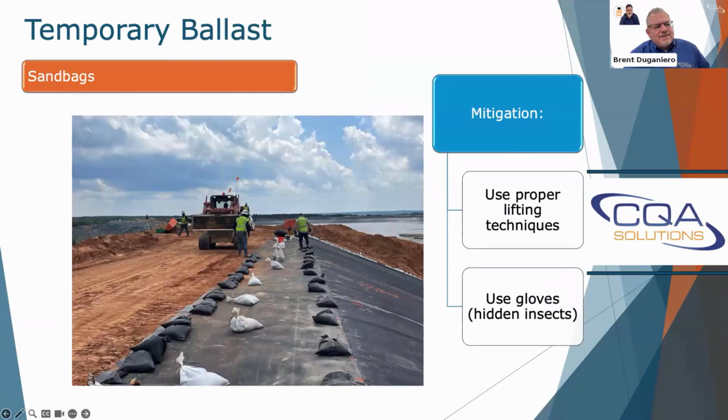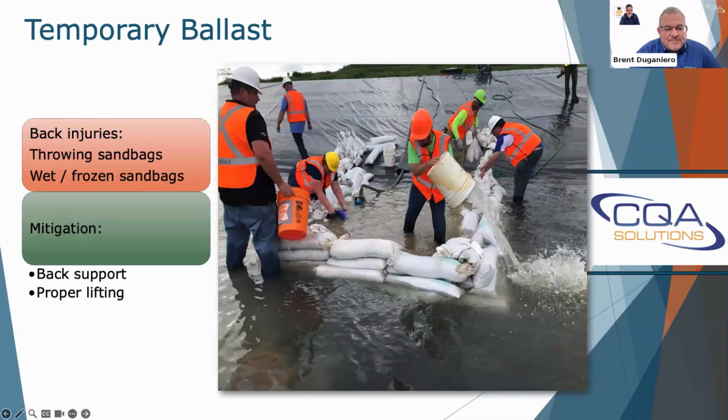Okay, temporary ballast. As we got our panels pulled out onto the subgrade, now we want to make sure they're ballasted in place. Sandbags is something that we often use. So we want to make sure that we're using the proper lifting techniques and maybe using a back brace. And again, the sandbags might be there for days to weeks at a time. You never know what's hiding underneath them. So make sure you've got gloves when you're picking them up.